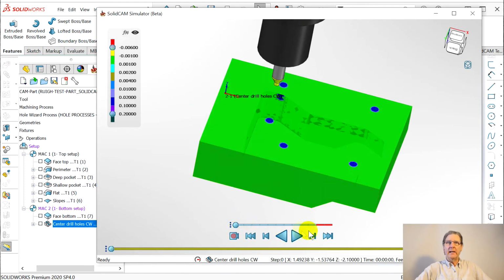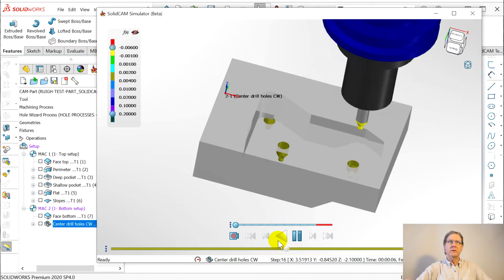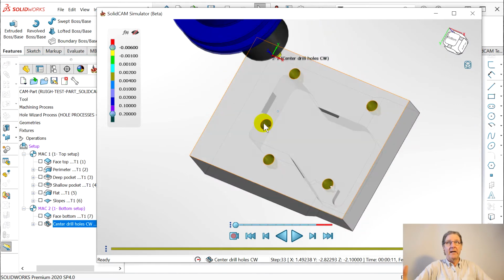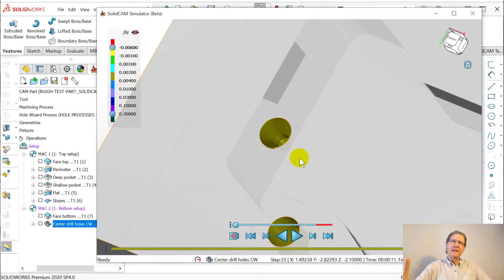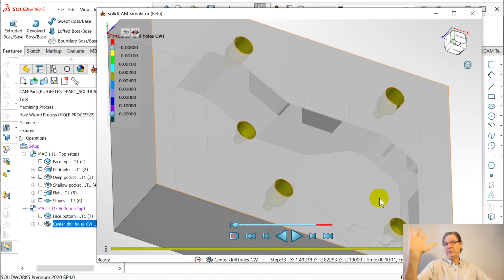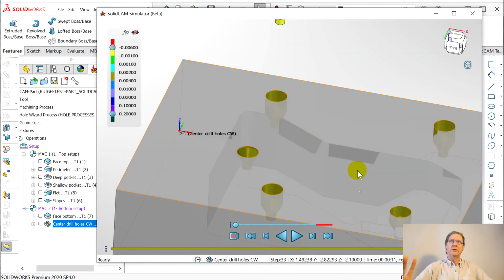Then slow it way down, and let's turn off the pretty. That was the compare function, right? It's green because everything's where it's supposed to be. Do it. See? You can almost see because I use this translucent stock. Oh, and you notice it hit that hole twice because it counted it twice. Automatic. Mastercam did the same thing. It did this one hole pretty shallow and it buried the others. So there's some software algorithm that decides how to treat blind and through and partially through holes. But in general, they're all way too deep.